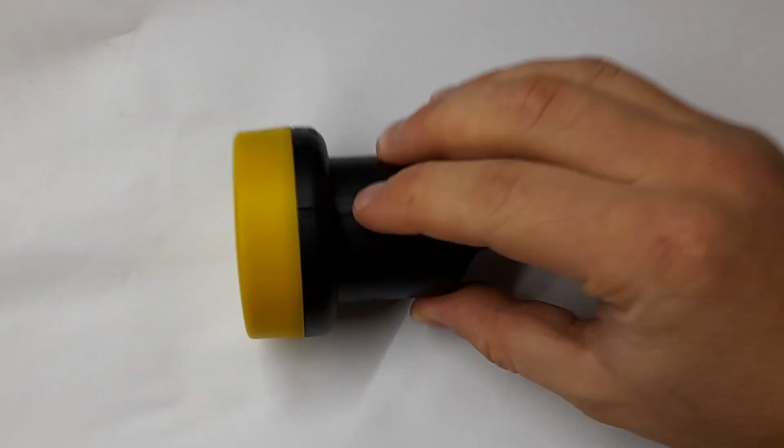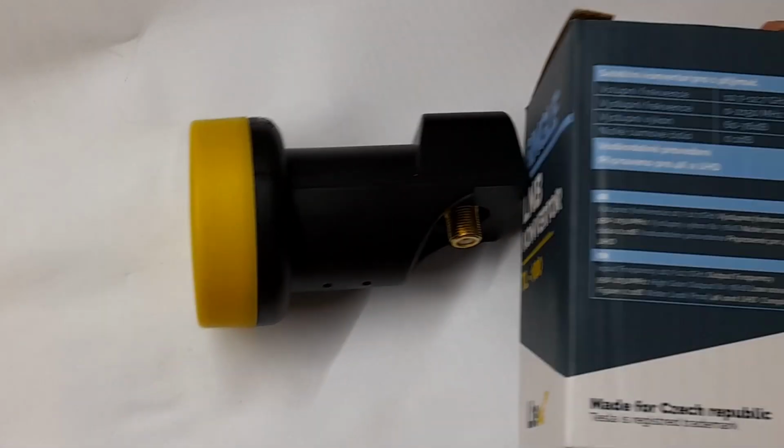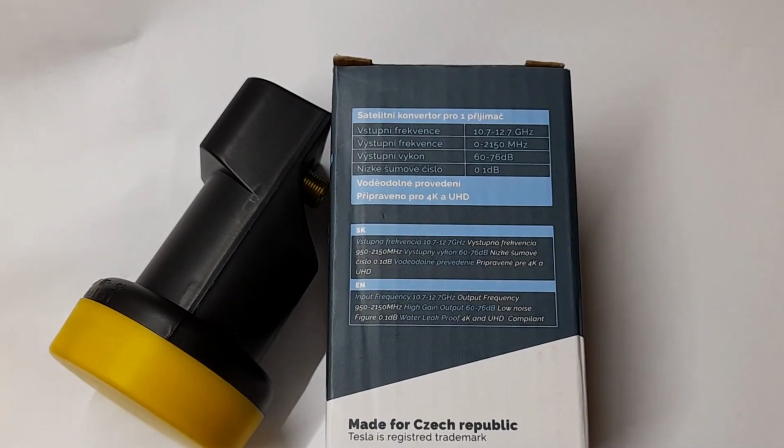This is quite literally the cheapest Ku-band LNB available for sale in this country brand new, and it only set me back around €4/$ in late 2022. To learn what kind of frequencies we will be able to receive with it, we will need to know a few of its parameters. First is the input radio frequency, or RF range, which is specified at the back of the box as being 10.7 to 12.7 GHz.